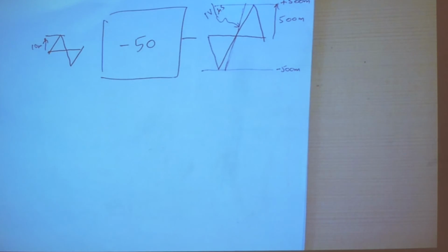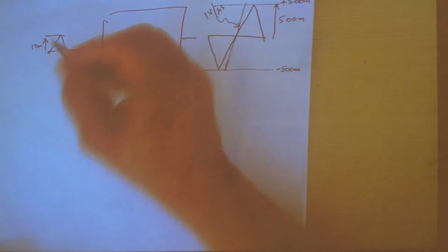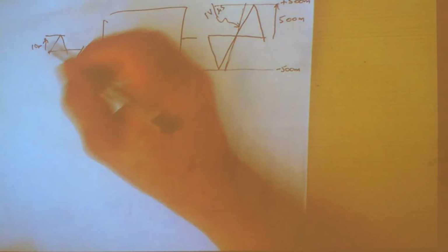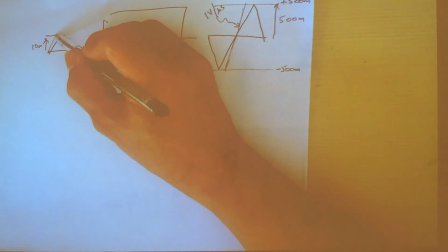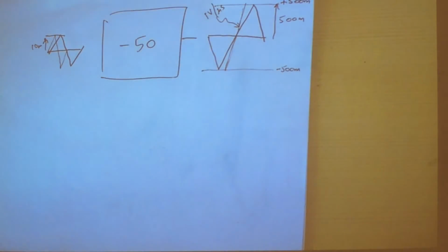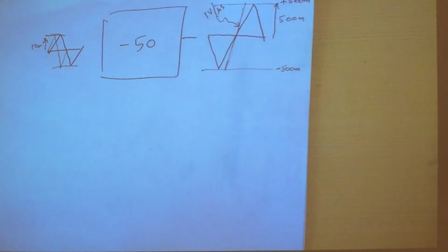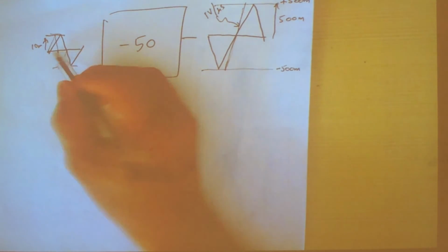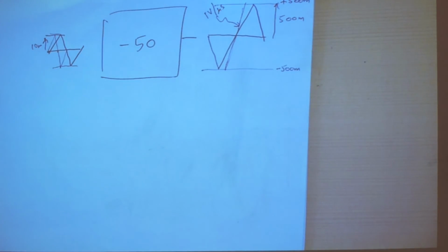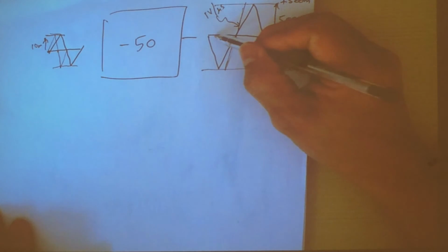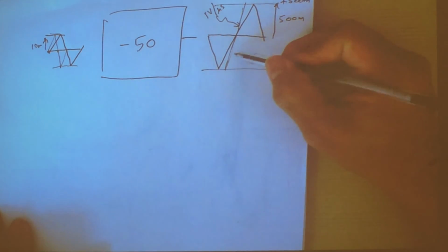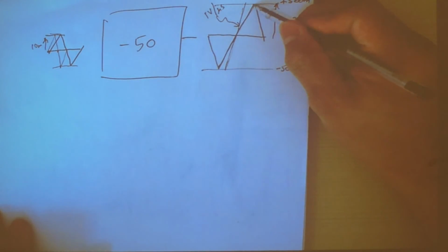And I'm going to increase the input frequency. Take the input sinusoidal triangular wave, I increase the frequency. Right? Same amplitude, I increase the frequency. As I increase the frequency, the zero crossing points get closer and closer to one another. Am I right? That's how we increase the frequency, right? So as I increase in frequency, there will be a point in which this slope becomes this slope. Alright?